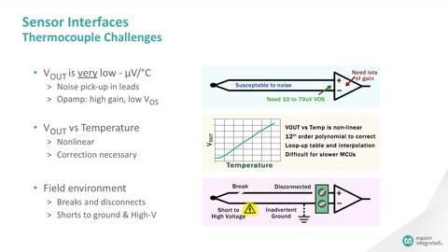The requirement for accuracy doesn't end with the input amplifier, but extends to the rest of the signal measurement chain. That includes the ADC and the voltage reference feeding the ADC. This requirement for accuracy and precision makes the design of the overall analog signal chain tricky, requiring a very careful design and close attention to the error budget.